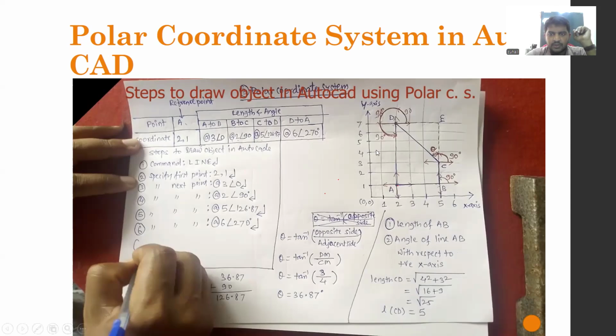Okay, first I am going to explain this one. For this particular drawing, what you have to notice is that the at command means a particular relative point. So for the previous point, you are using at. You are considering the previous point's XY coordinate as 0, 0. That is what you are using, the at command.